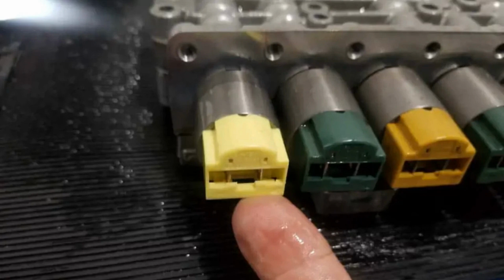A solenoid specially designed to perform the most resource-intensive work of all other types of these devices. It acts on the torque converter clutch, which locks and engages, increasing the efficiency for special sport modes of automatic transmission operation. This element is the weakest on certain automotive torque converter units because hot and unfiltered oil flows through it. Shift solenoids, or shiftovics, act as switches. Structurally, the simplest device among analogs, which is responsible for the effective and timely automatic switching of the necessary gears in the box.